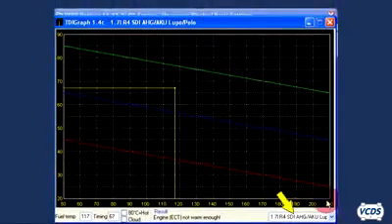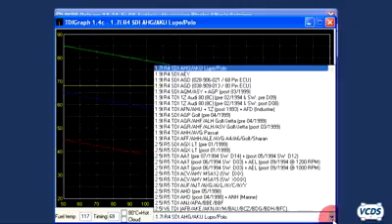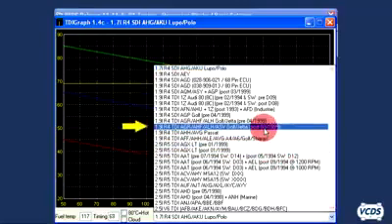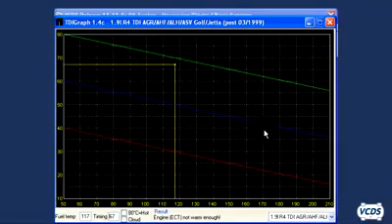You will need to select the correct engine from the list in the lower right corner. Different engines have different specifications, so locate the correct listing for a 2002 Jetta with a 1.9 ALH engine. Note that the ALH engine is grouped with other engine codes, and the date of manufacturing does matter. With the correct engine listed selected, the scale on the screen will change.